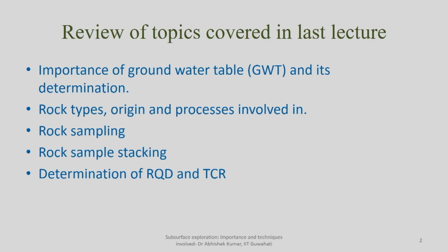And then its determination depends upon what kind of soil is available at depth below the groundwater table. You may require a few hours, you may require a few days, for the groundwater table to reach equilibrium, and then you can report it: this is the equilibrium groundwater table at your site of interest.